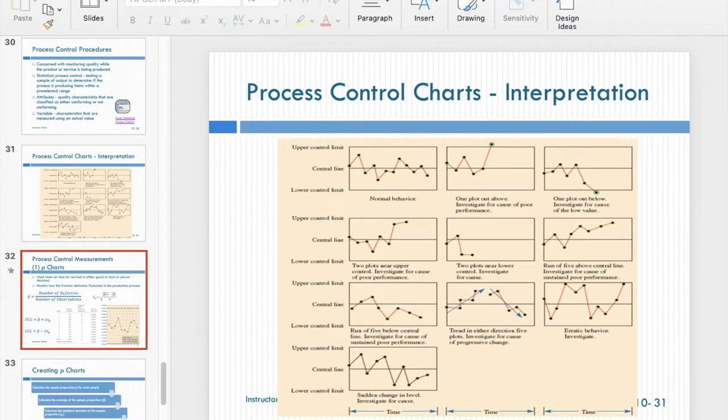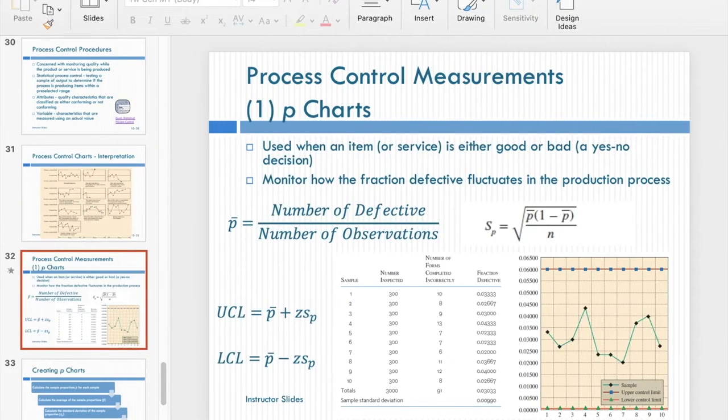Okay, now let's start to talk about these 4 different specific situations. Actually, these 4 different specific situations are very standard. Let's start by looking at the P chart. What is meant by a P chart? Let's say you are producing a product. You are inspecting a product, and you have your standard to differentiate whether every unit of product is defective or not.